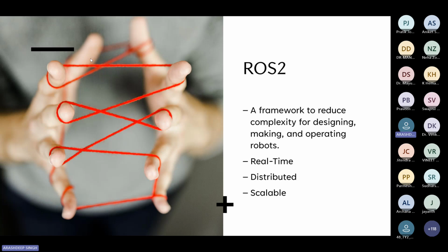As we have seen, robots are complex systems requiring different components. They need computing power, they need algorithms to make decisions, they need manipulators to actually manipulate something in the environment. For mobile robots, the basic purpose is moving from one place to another, carrying some load. For that we need navigation, and there is a dedicated navigation stack based on ROS, which we call Nav1, Nav2. Similarly, for manipulators, there is a dedicated stack, MoveIt and MoveIt 2. So ROS helps us integrate our needs from the robots into one framework.